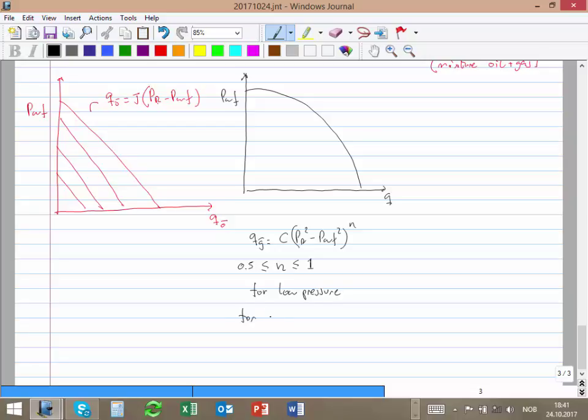For medium to high pressure, you have to use another equation that, instead of using pressure, uses the M function, the pseudo pressure function. Did you cover that also? No? The pseudo pressure function, where M of P is equal to 2 times the integral from P ambient, the standard conditions, from 0 to P of P over mu Z dP. Did you see this equation before?